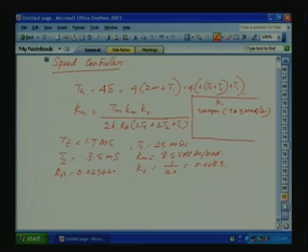So, the moment 52.3 radians per second comes, we want a maximum voltage of 10. So, all our control is plus and minus 10. So, the gain K1 is equal to 10 volts by 52.3, so it will be 0.19. K1 we got. So, let us write K1 is equal to 0.19.